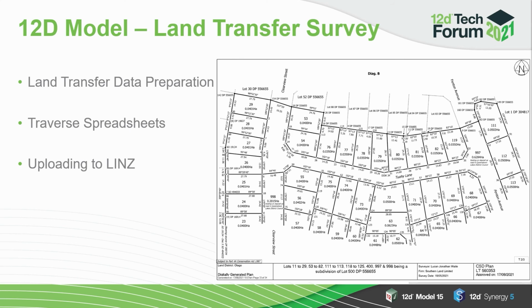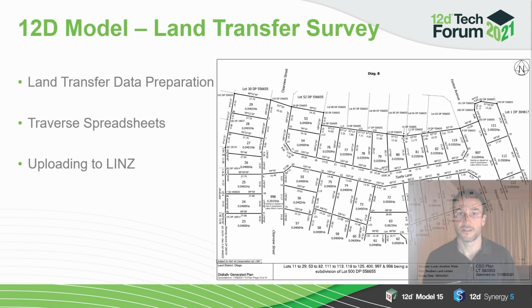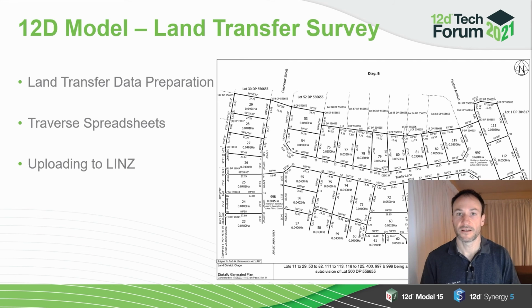We do all of the land transfer surveys from 12D model. Our data prep is all getting produced in the Traverse spreadsheets, and that's all getting uploaded into Land Information New Zealand via XML. Super handy when you've got the cadastral surveyor doing all the pre-calcs and you're just checking that everything's going to work. You can share those models in across your design project and see where exactly all these pegs are going to land and work out any clashes during the construction.